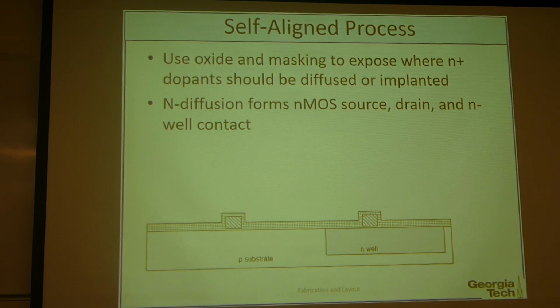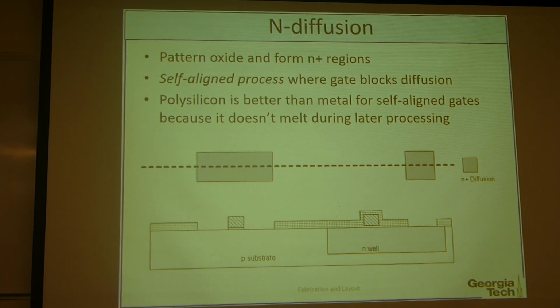And it is time to make a source and drain junction. To make it, we need another oxide on top of the silicon wafer to block the unwanted area from being doped. So we deposit oxide here again. And then we use the source drain N-type junction mask here.